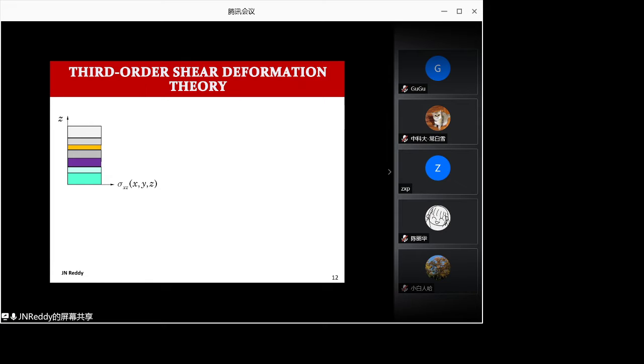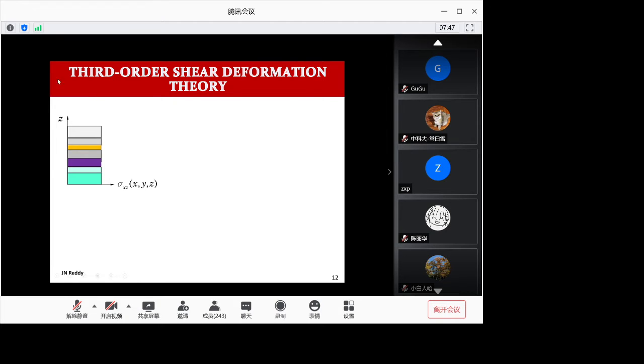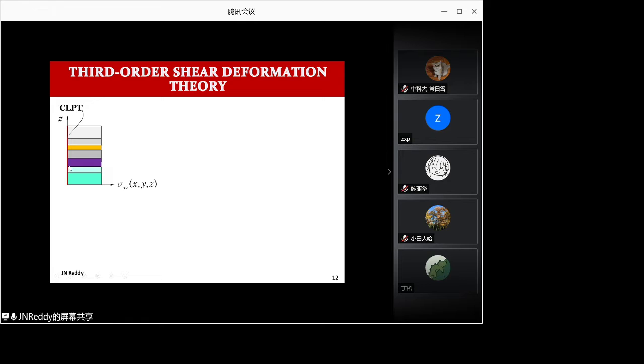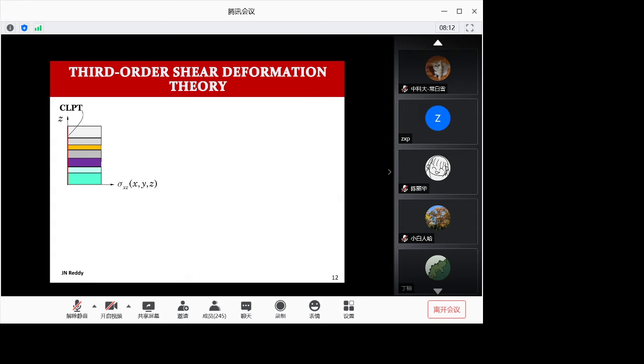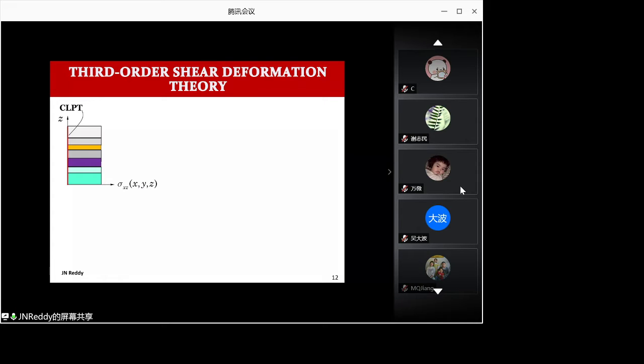the orientation is different. So when we use the standard theories, in the classical laminate theory, we assumed that the transverse line, the one that I just showed in red, is one straight line. So you remember yesterday I was talking about straight lines remaining straight and inextensible, and then they rotate such that they remain normal to the mid-axis during the deformation. So that makes the theory a little bit over-stiffening the structure. That means we are modeling the structure stiffer than it is.